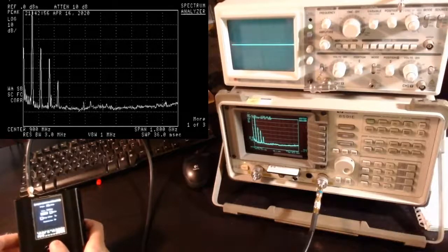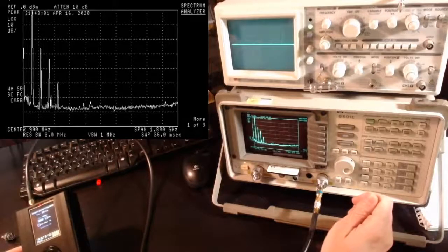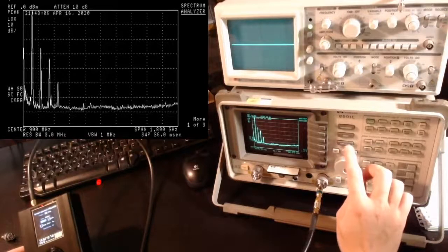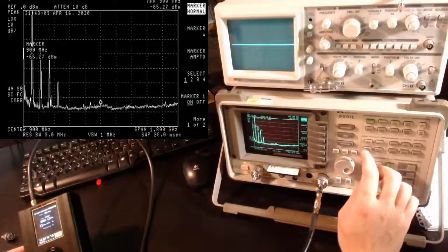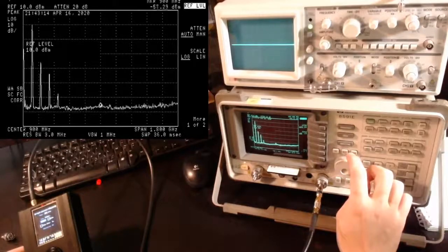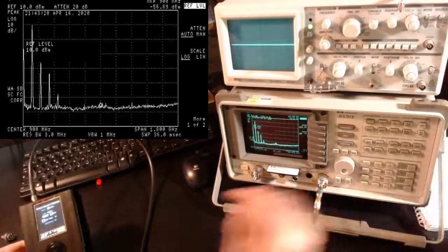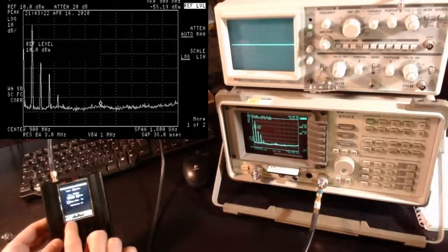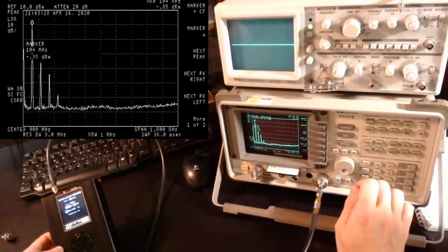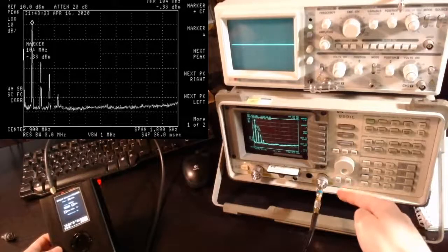and there we have our signal. So let's try to see here. Wait a second. So the markers. So let's lower the amplitude slightly. So the reference now is at 10 dBm. So I'm outputting at the maximum power possible, which here on the Portapack is named 47 dB. As you can see, if I do a peak search, I'm getting my signal at 100 megahertz at about 0 dBm. So in reality, since we are attenuated by 10 dB, it's a 10 dBm signal.